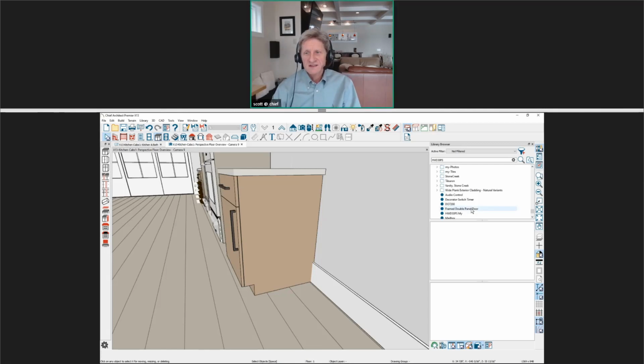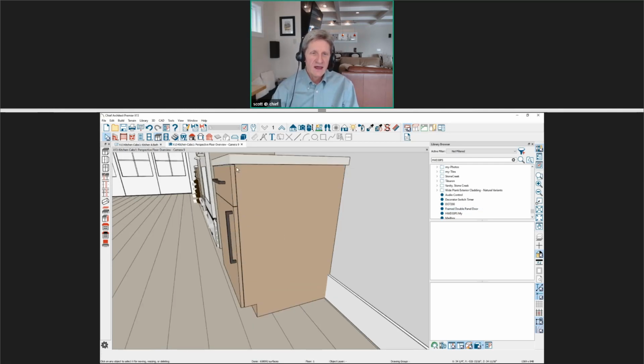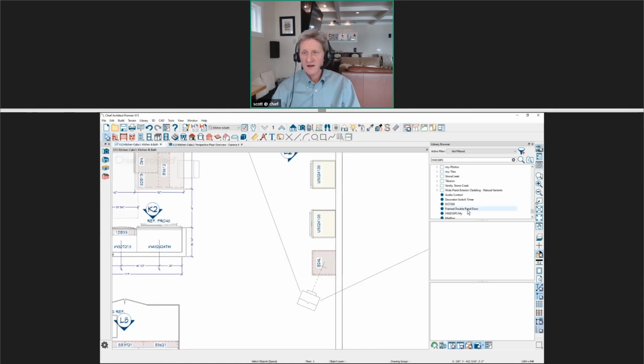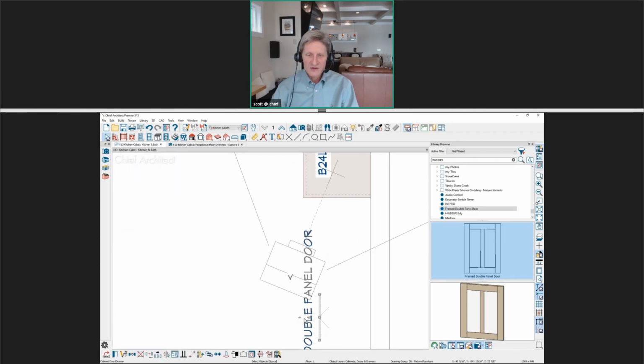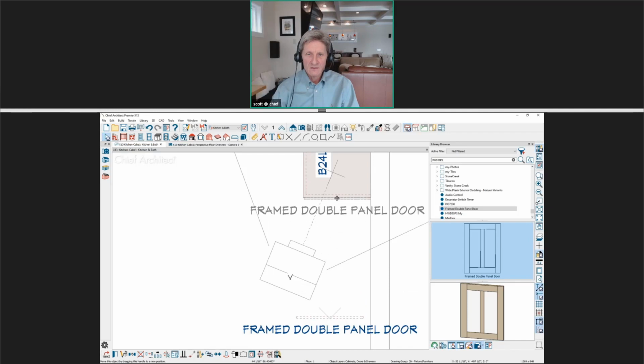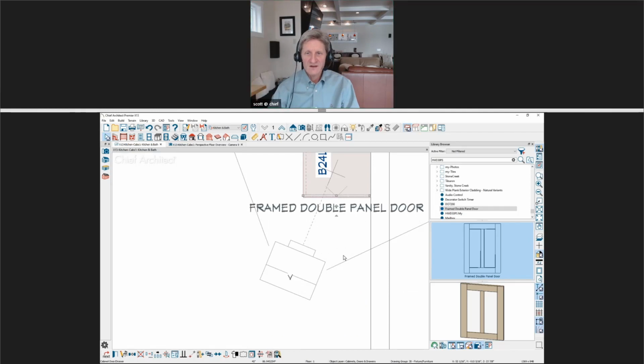Yeah, I think that's the easiest way to do it because, again, when you select this cabinet, it's going to end right at the edge of the box. And so if you want it to extend past the box to the thickness of that door, you'll want to place a side panel separately, and you can easily do that. It sounds like you're familiar. You just grab a panelized door. You've got these panel doors. You can rotate them around and then position them however you want right against that cabinet. And that's the easiest way to do that.